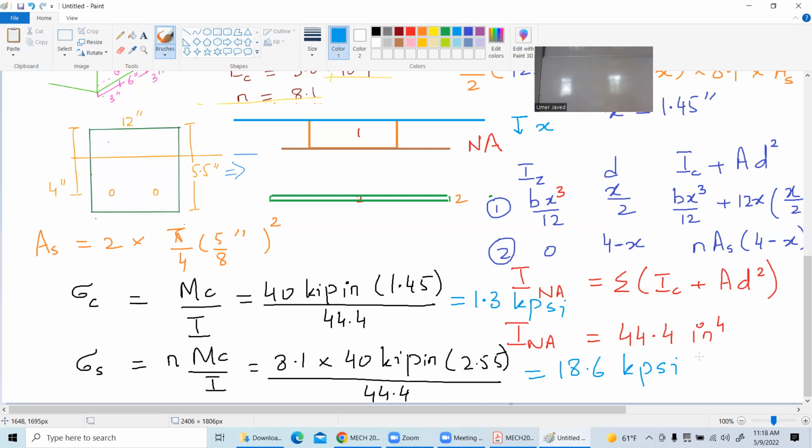For the second part, below the neutral axis, we made a thin cross-sectional area. Right? Because we made that little cross section, section 2, the green line, that green little rectangle, because we don't know how to deal with the fact that it is composite. It is composed of two different materials. So I removed all the concrete. I removed the rebar and I filled everything with concrete. Okay. Hypothetically. So the small cross-sectional area includes the concrete and rebar.